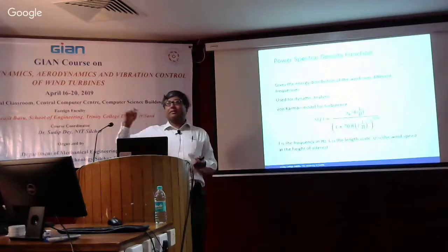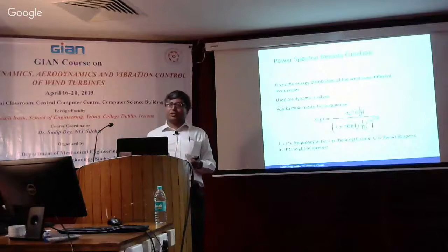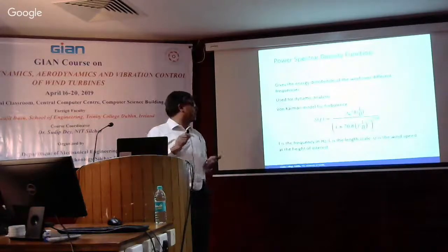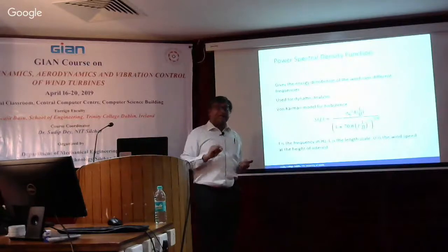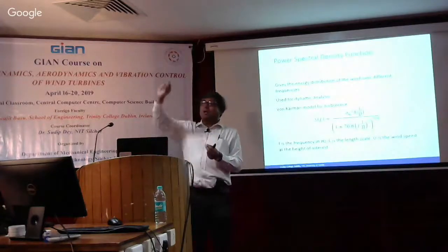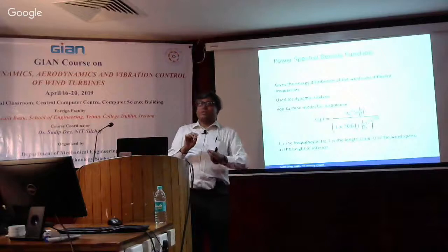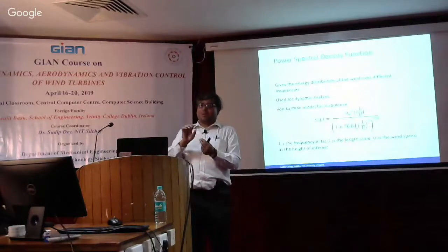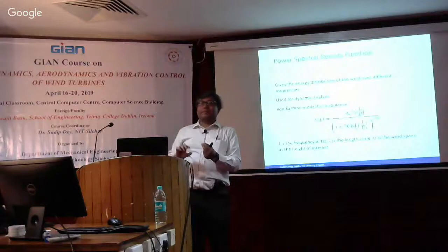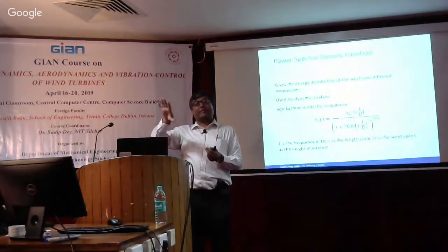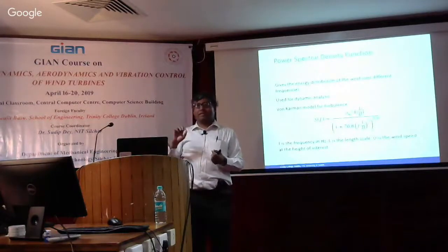That generates the random wind fluctuation. Now, that is for a particular point or location in height. You also know the power law, so now you can also generate how the wind time histories are going to vary along the height. Okay. So this is how you can generate the time history of time analysis.